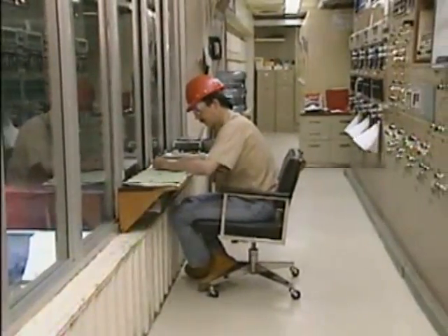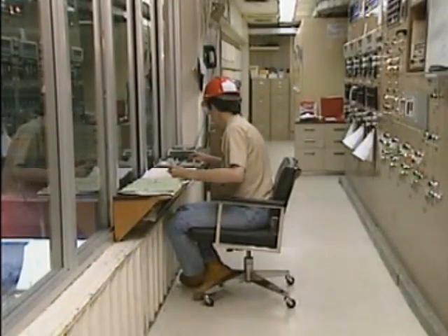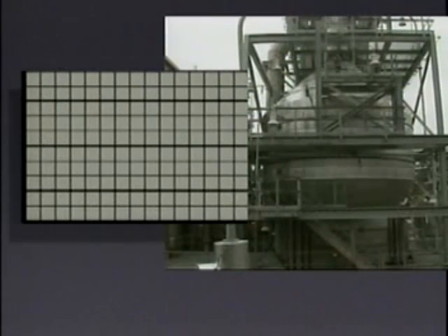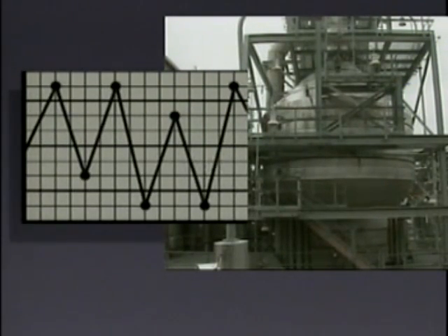These laws have to do with the probability of something occurring either naturally or because of an outside influence. In any process, there is always some amount of variation. Because of this natural variation, no product is exactly the same all the time. But if there's too much variation, there's a problem somewhere in the process. Too little variation may seem like a good thing, but statistically it shouldn't occur under normal circumstances. So too little variation could also indicate a problem in the process.